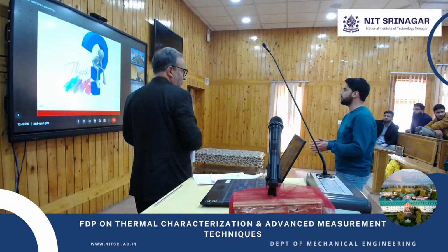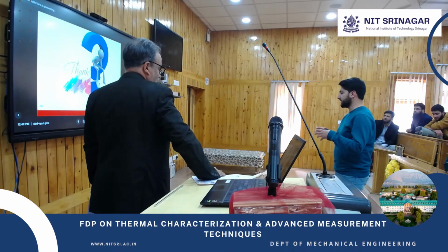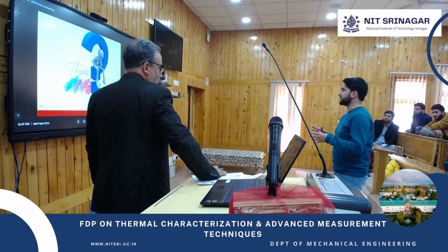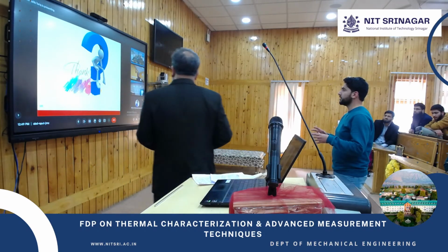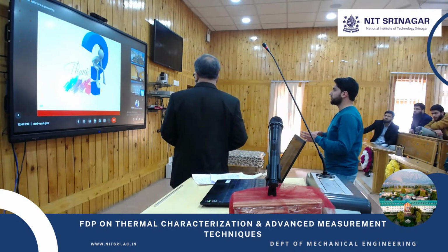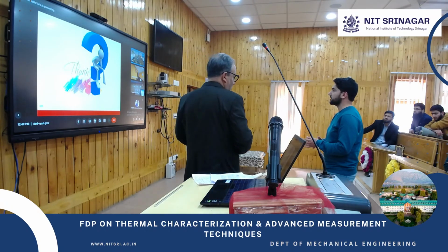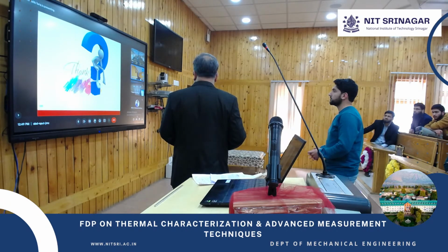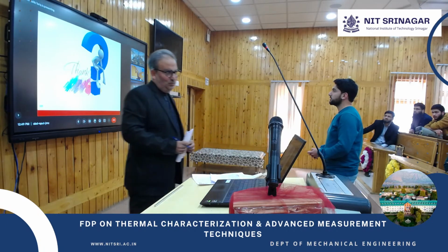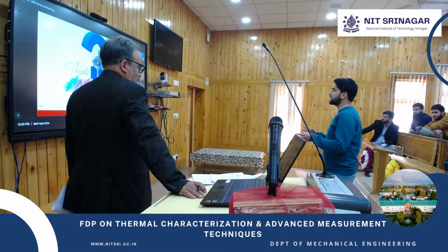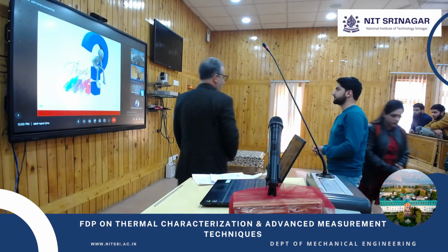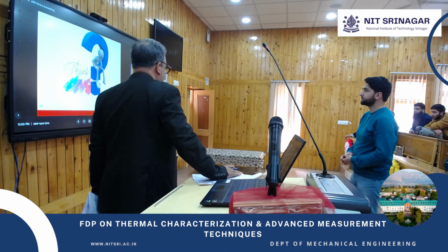Sir, my second question is with regard to measurement. I'm using a cavity, a cube for example, and it encompasses a fluid inside it. We are facing the problem of measuring the temperature profile within the system. Do you have any idea how we can measure the temperature? We cannot use an IR camera because the acrylic doesn't transmit. For a cavity, I think thermography and interferometry are the standardized techniques to study the convection pattern inside the cavity. It has to be made transparent. I've used that, but it is a very old technique. Now you can see things in a better manner with the color shading and all that.